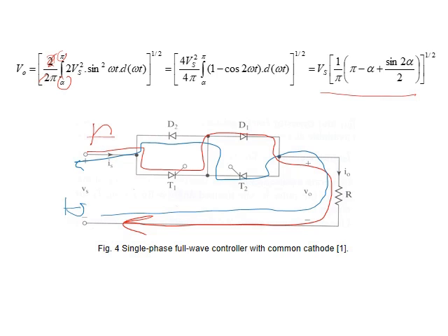You see? Now you may ask, what is the benefit of having 4 switches? Now with 2 diodes and 2 thyristors, these gates can be triggered by one circuit, and whichever is in forward bias will conduct. So I reduce the triggering circuits by one. Definitely the losses will be higher, because at any time 2 switches will conduct. As an example, this one and this one conduct together, so there is a drop here and a drop here.